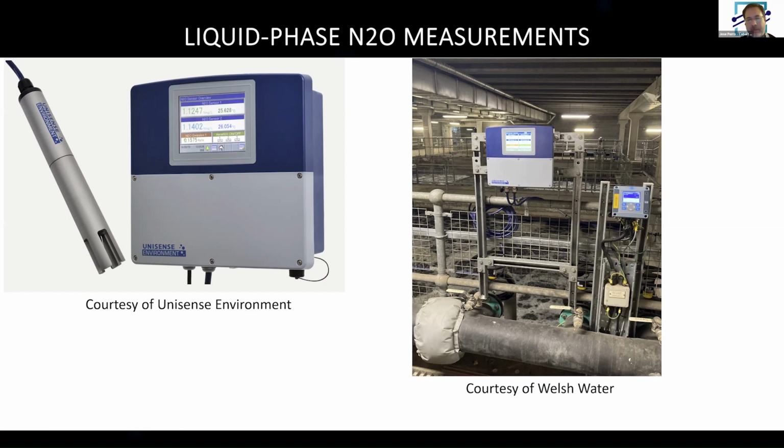It's not telling you what the emission actually is, but with the airflow data from the plant, we can calculate what the emissions are using mass transfer equations and assumptions in terms of mass transfer coefficients, what the KLA value is for N2O. And if those assumptions aren't quite correct, you could have some error in what emissions you're actually calculating.